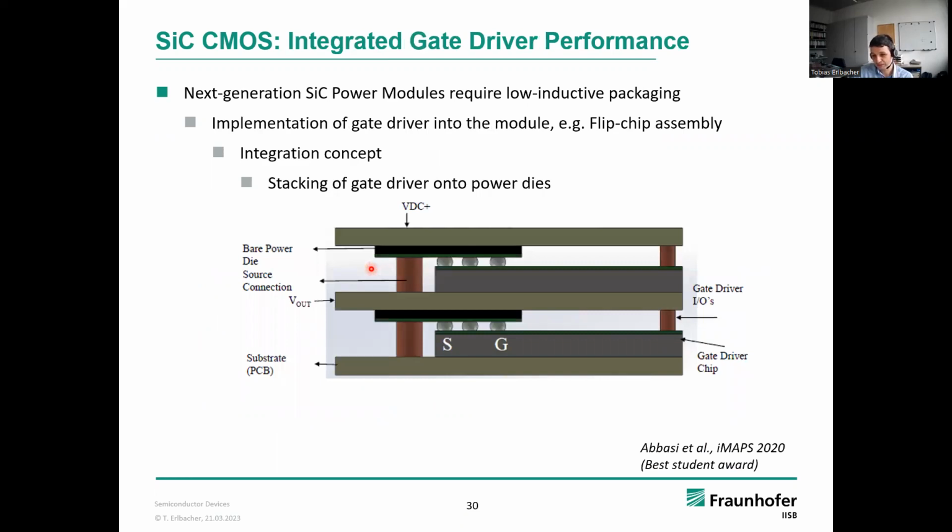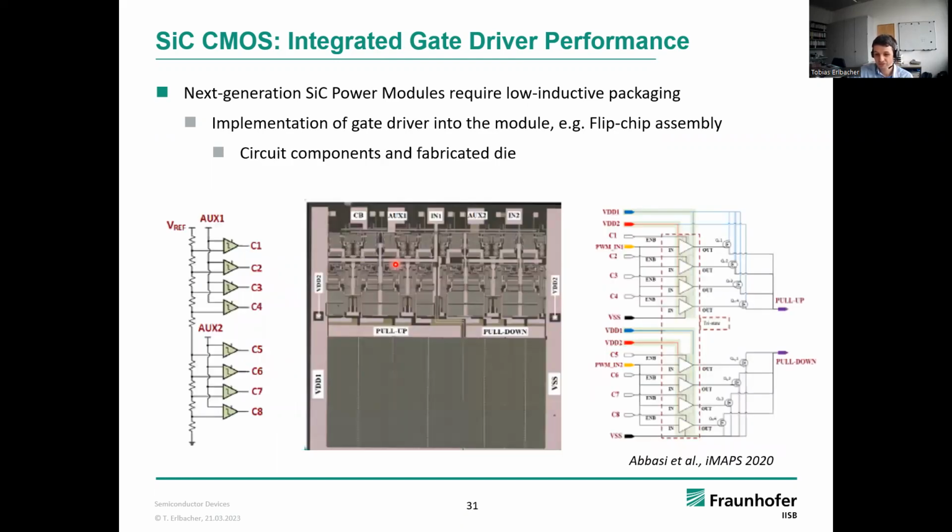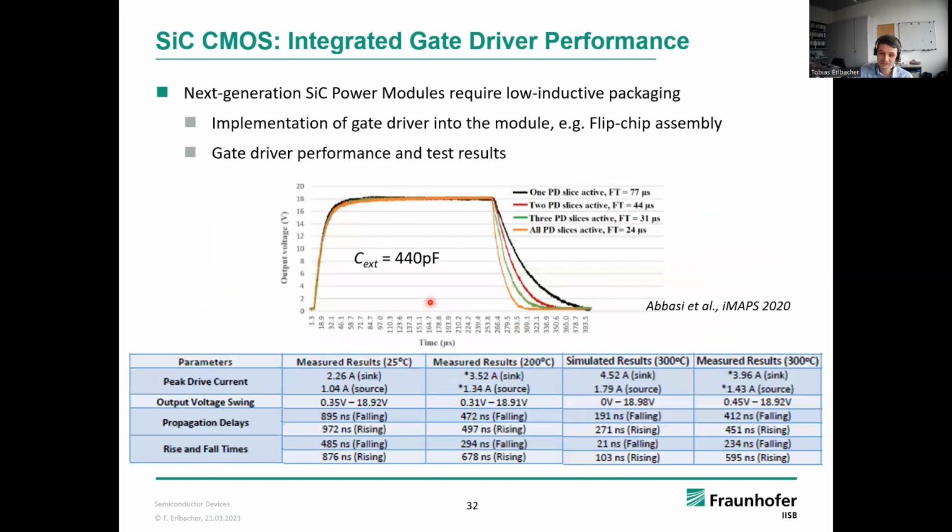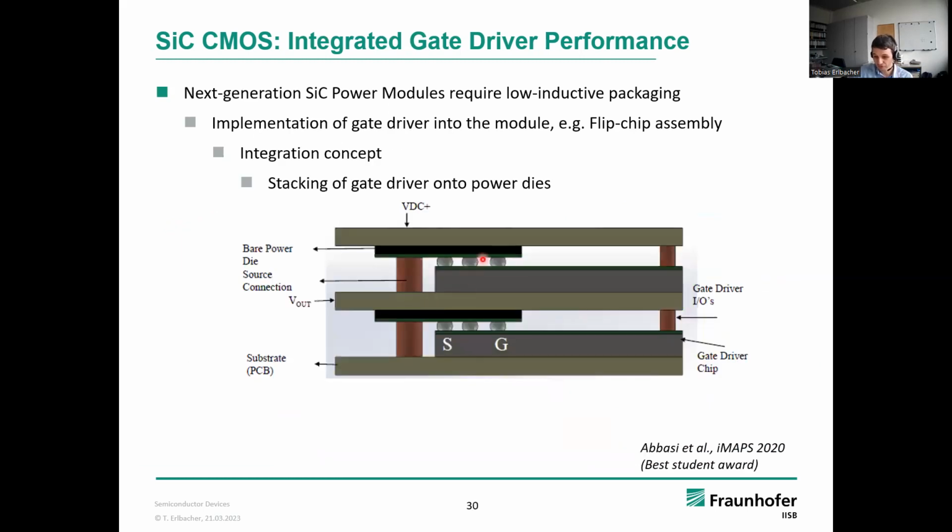And this also includes integration, like in a power module where you have a silicon carbide IC. You can actually stack integrated circuits on top of that with flip chip assembly. So there has been work to manufacture integrated gate drivers in silicon carbide that were then investigated and characterized as well. So this also, of course, leans towards the combination for silicon carbide power modules with very low inductive packaging as well, where you also want to exploit the high temperature capability of your power switches.